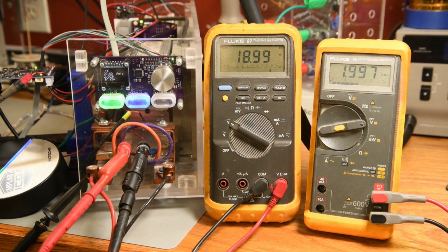And at 20 amps, there's about 5 volts of 120 cycle ripple. The voltage value I send to the display is averaged over about 82 microseconds. So sometimes it gets a value from the peak of the ramp and sometimes it doesn't. That is something I do need to fix.